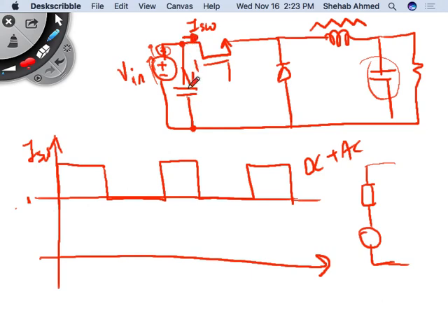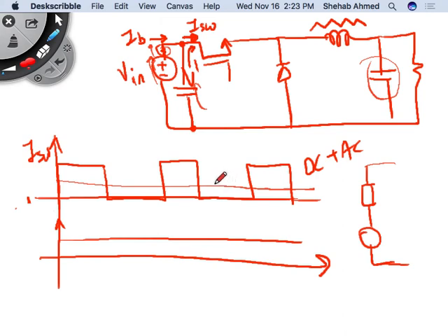If I put a capacitor here, then any current flowing through the switch, which will eventually come back through my circuit, will have to do what? Will flow through the capacitor, assuming an ideally large capacitor. Which means that all the AC current will come through this capacitor and allow me to do what? Allow me to bring in nice average battery current from here. So the average value of this current will now be your battery current. This is I battery.